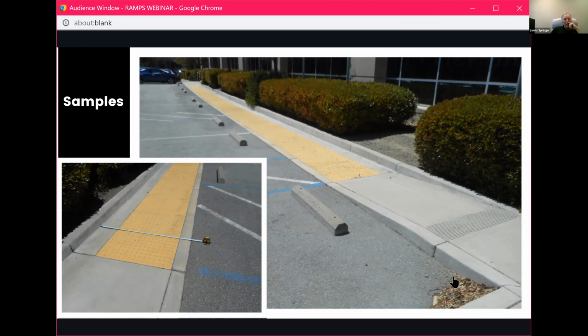I agree with you, for a short distance. The detectable warning, in my opinion, is an architectural barrier we are required to put on surfaces, but it can still be used as part of that 48-inch width. Okay. When the new code requirements came out, they did add the 36 inches, which is really wide enough for a wheelchair to go down and not have to interact with the bumps.